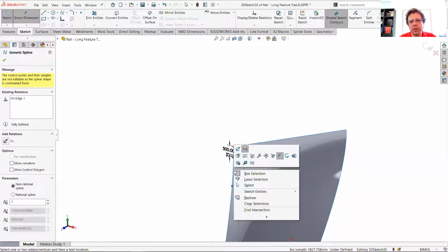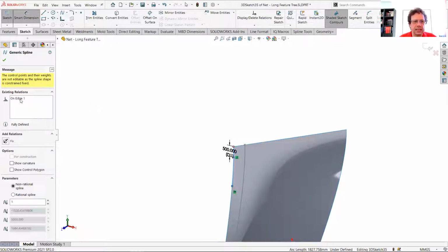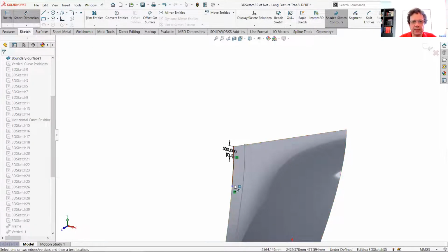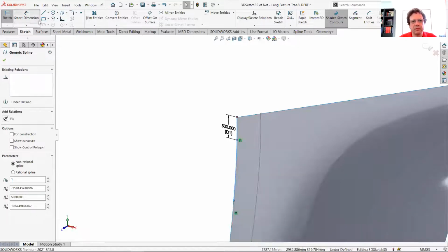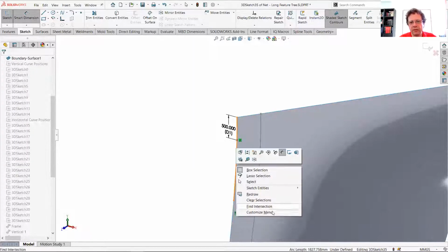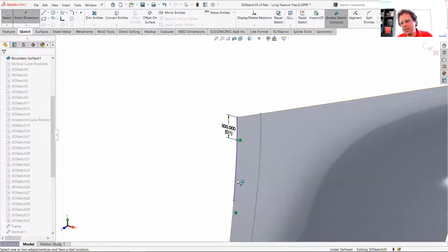What other options do I have for this spline? Other than deleting the on edge, let's delete that and see what happens. Let's see if it becomes a regular spline that we can try to apply some type of dimensions to, but as you can imagine, that kind of defeats the purpose. So it's still, let's see if we can convert it to a spline, right? So crazy limitations. If somebody has a computer handy, maybe write an enhancement request to allow splines that are obtained from the convert entity command to apply dimension to. Wouldn't that be cool? That would be so nice.